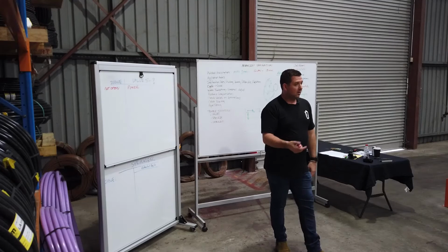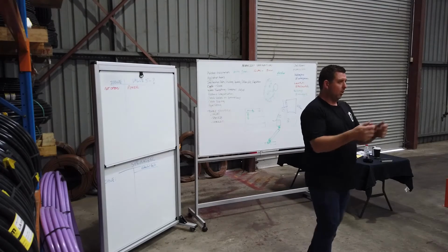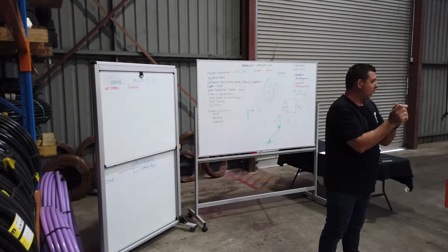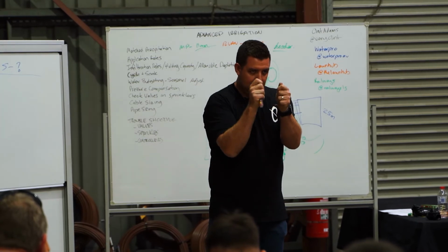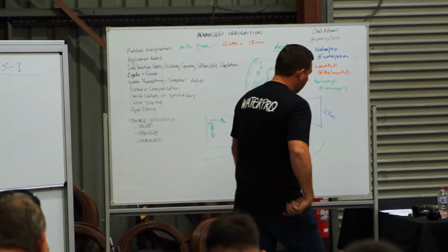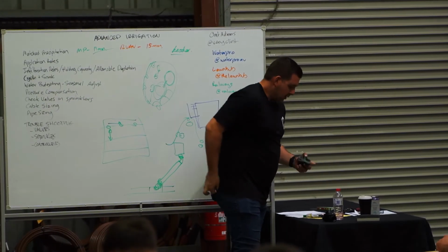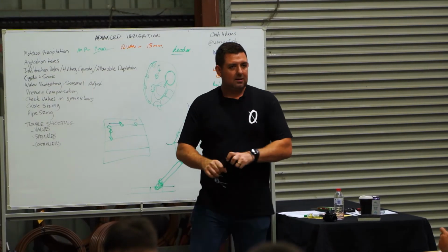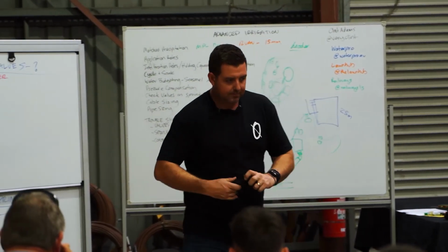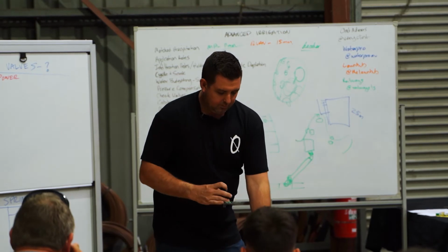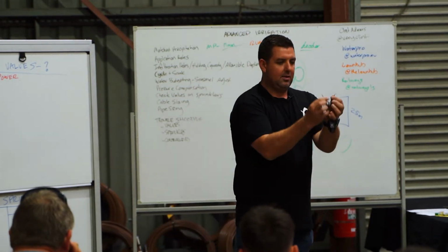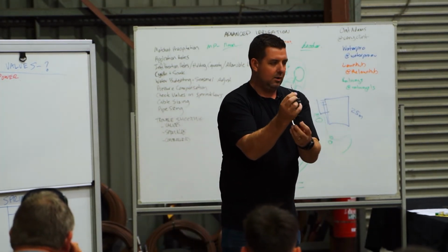What I used to do is I'd just get a spare coil and walk up to the controller while valve 1 was meant to be on, and I tap the coil. So a coil is this, and it'll click and buzz if it's getting the right amount of power. It's a bit of a bush mechanic kind of way to do it, but I'll just go like that, and then just test it, and you'll hear it buzzing.